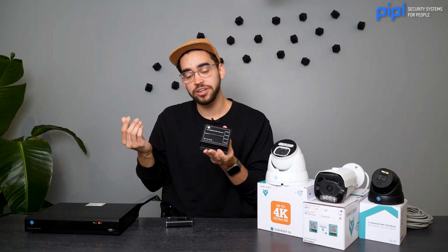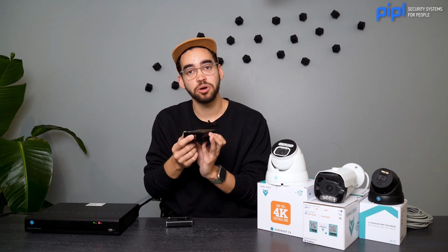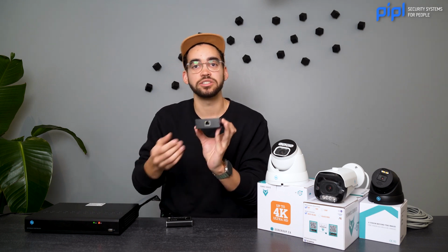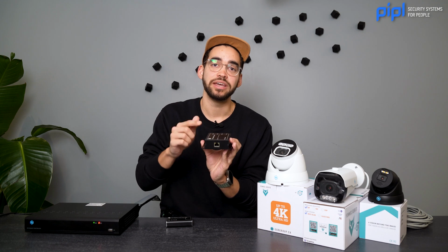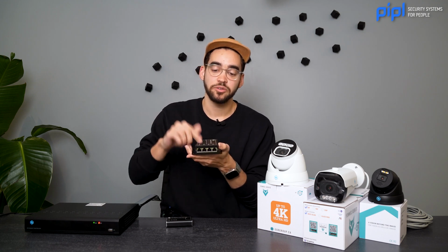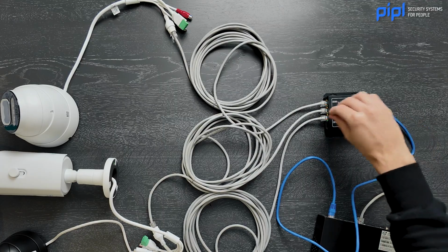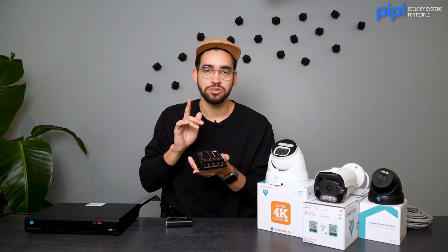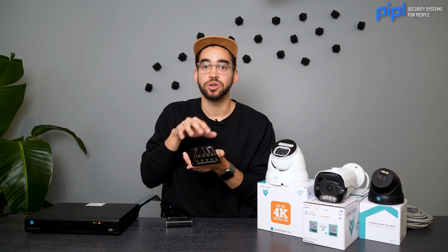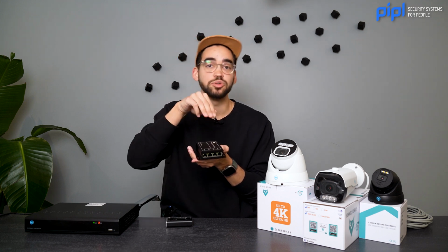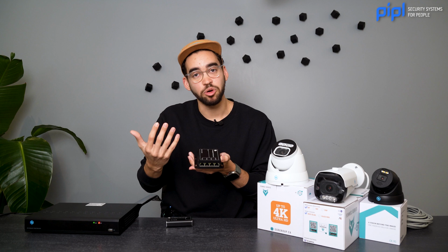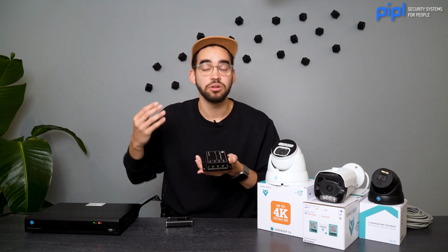So again, really nice solution because with only one cable, so reusing a cable that is already installed and going into the PoE input, you can connect 4 more cameras through the output. And again, it splits the power. So that's something to keep in mind. So it's 90 watts. So if you're using 3 PTZs, you're going to use 3 ports. But you can use all 4 ports if you're using regular cameras, for example, or if you're using a video intercom and all other security equipment. Just make sure to look at the datasheet to not exceed the power limitation of your PoE extender.